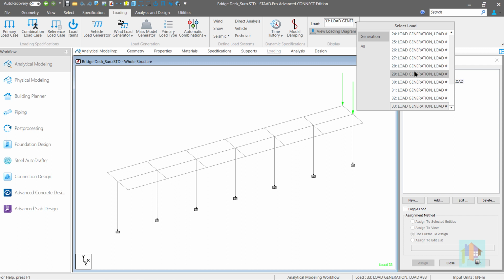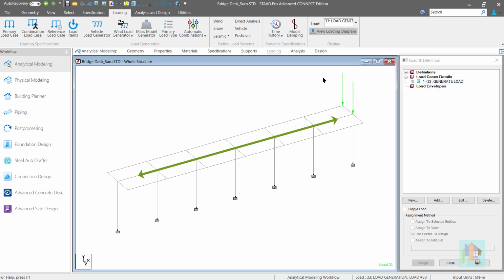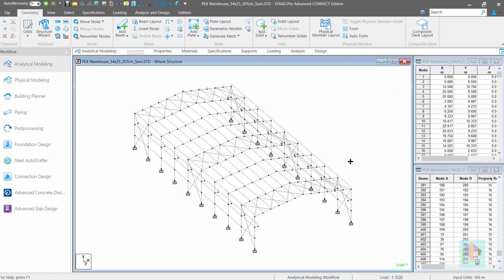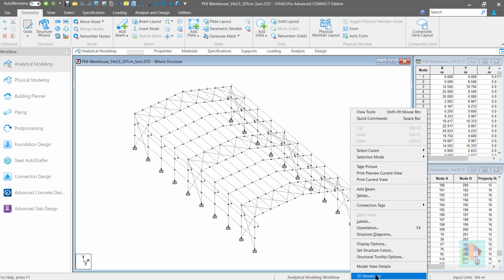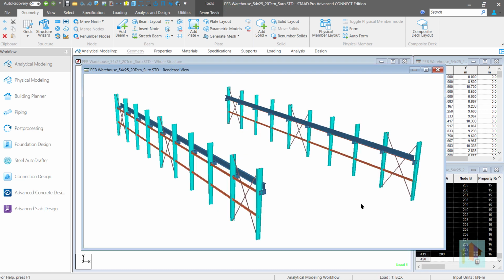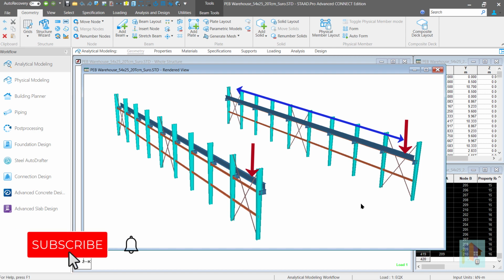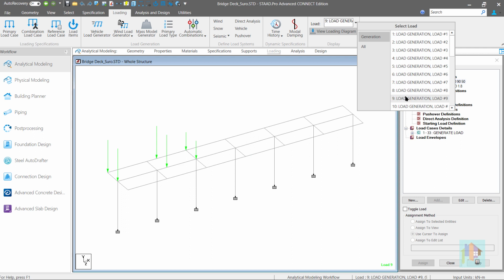Note that if the vehicle does not cover the entire length and travels within a safe distance, then this load calculation logic is not applicable. For example, normally any EOT crane does not travel till the end of gantry girder. There is a safe edge distance, and to apply the crane load correctly, we need to calculate the traveling distance of crane. Can we apply this load from right to left or combine multiple vehicle movements, which is a realistic condition for any bridge with two-way traffic?